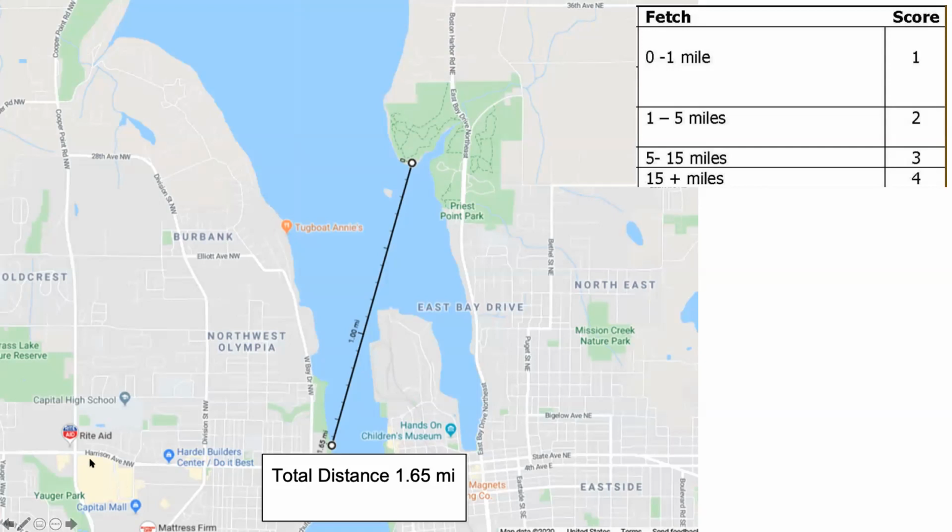So in the previous module, we touched on measuring fetch. We did it a little bit earlier and what that means as far as wave energy. And we do the same reduction here in fetch for winds from the northern quadrants, unless that happens to be the prevailing wind direction. So to further clarify the categories, they're based off of studies in Puget Sound and Japan that have documented the wave heights that will cause bluff movement, and the fetch distances associated with those wave heights.